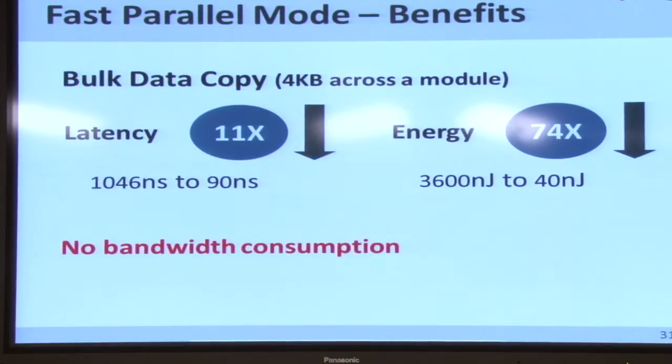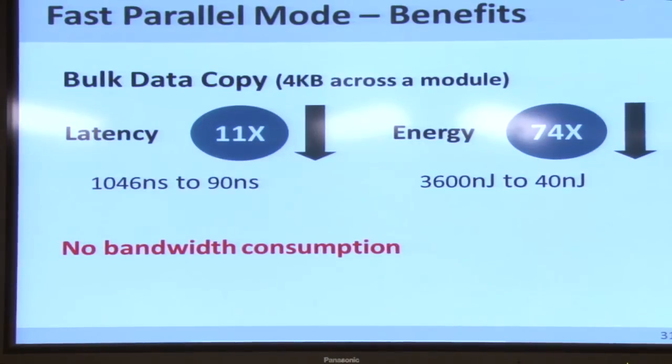The reason is, if I can do the in-cache copy, I can do both the DRAM copy and the in-cache copy simultaneously. I don't have to wait for the in-cache copy to complete or the flushing to complete before I do the DRAM copying, right? Because if I'm doing the in-cache copy, it means I'm also creating the dirty block for the destination row. Now, it doesn't matter what the destination value is in DRAM, right?